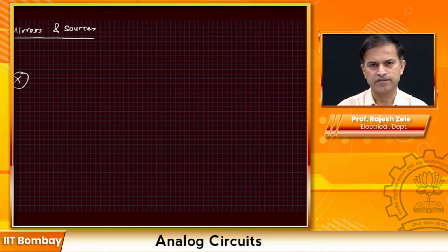Generally, the way you distribute currents on a chip is that in one corner of the chip there is a block that generates current references. The purpose of this block is to create current, and we will discuss later how you generate these references. In this case it's a PMOS transistor, and when everything is connected properly, it will give you different values of current: this will be IO1, this will be IO2, and so on. Instead of transporting voltage to different locations on a chip, you would rather transport current, and it has certain added benefits, which is what I'm going to show you.